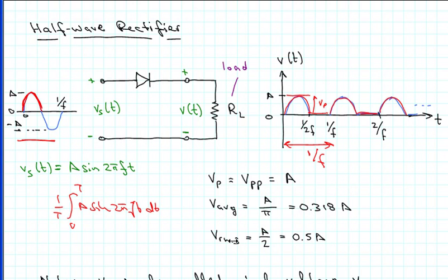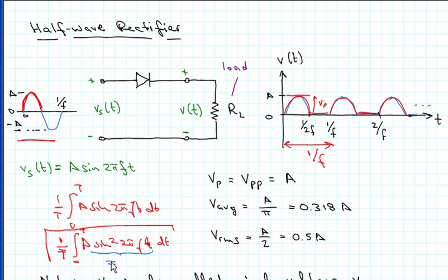And the VRMS voltage, so now you're taking the sine squared here, A times sine squared 2 pi ft dt, integrate over that from 0 up to T, divide by the period, and then take the square root of it. Use the trigonometric identity that sine squared of 2 pi ft is equal to 1/2 times 1 minus the cosine of twice the frequency, so that's 4 pi ft.